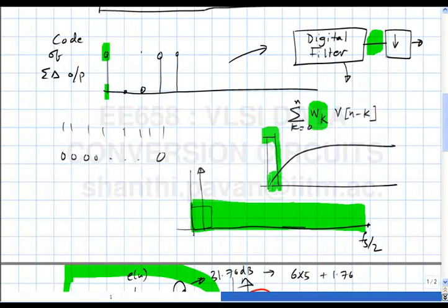So, the short answer to the question is that beyond a certain precision, okay, you can't do any better than the inherent quantization noise within the signal band. Okay, if you quantize the coefficients, you're probably doing as well as or slightly worse than what you would do with infinite precision coefficients.